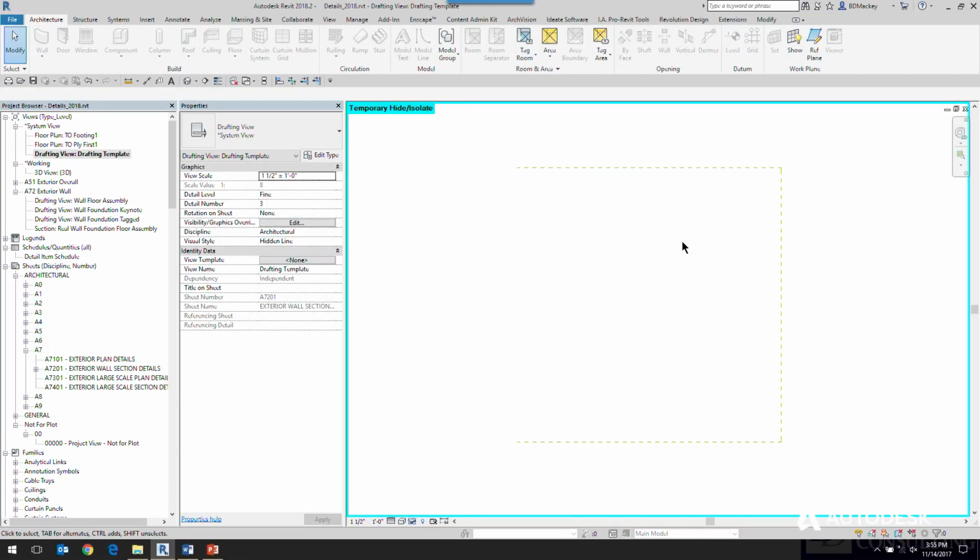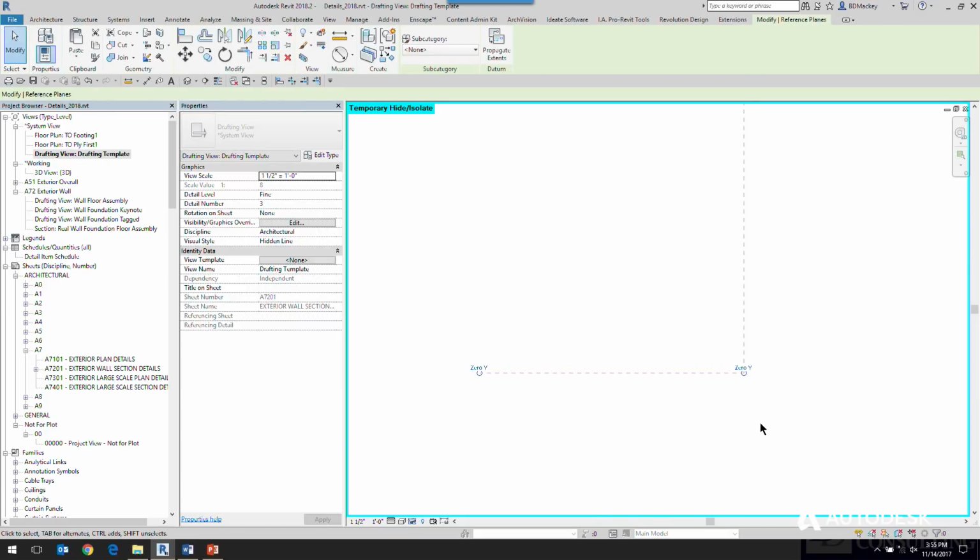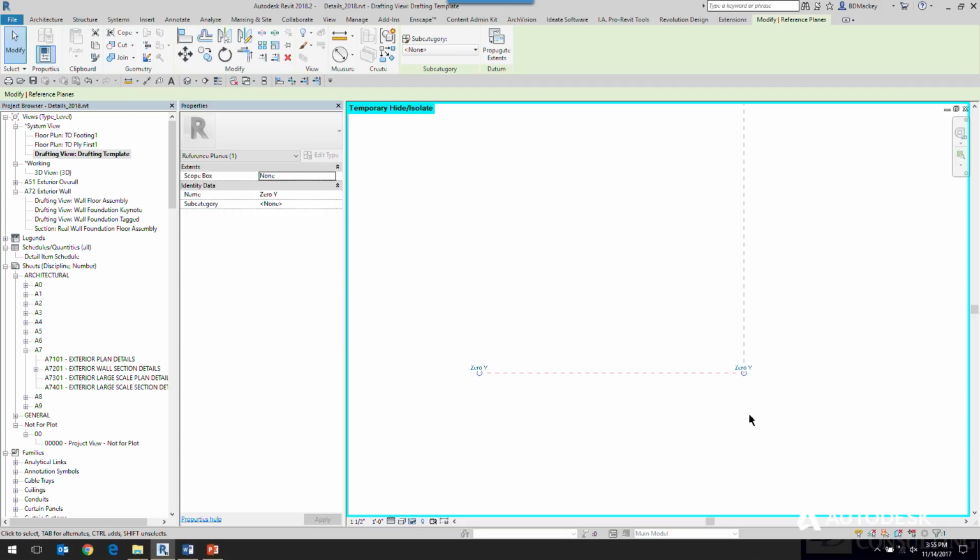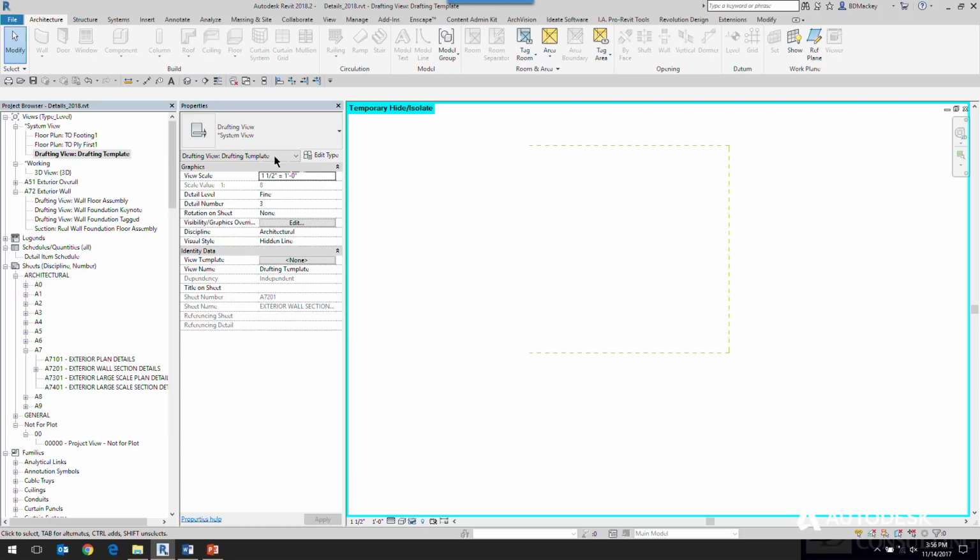The other reason is, for anybody who's ever been in one of my sessions, I have a type A personality. I also set that up to come into 0,0. So this is the 0 plane in the Y, and this is the 0 plane in the X. If I ever were to export this out to AutoCAD or any other utility, I'd know it's going out to 0,0. So there's another reason behind the scenes, more because of my type A personality, but it is nice to have it snap on the sheets as well.